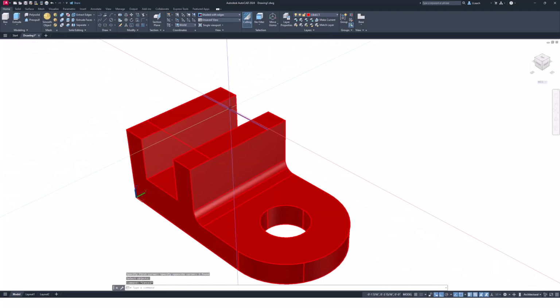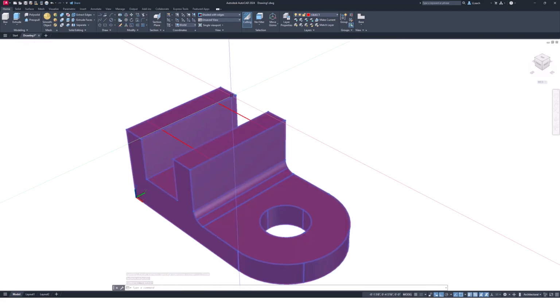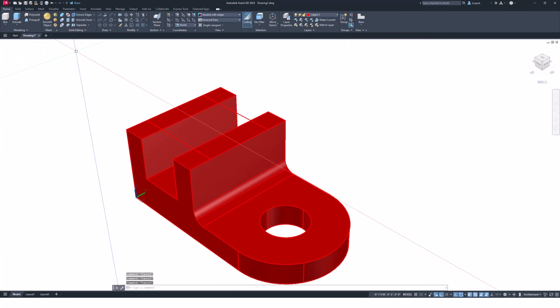And then what I want to do is create a polyline from these 4 lines, because I want to join those lines together. So I'm going to type in PLINE, press enter, select one of these lines here. Oh wait, that's not what I would do. Forget what I said. I don't want to make a PLINE. I want to make a polyline edit. So I'm going to type in PEDIT here.